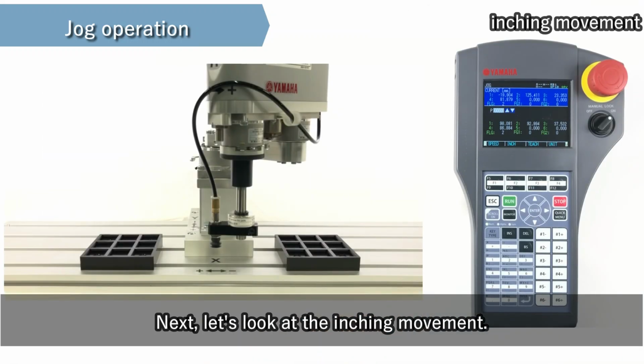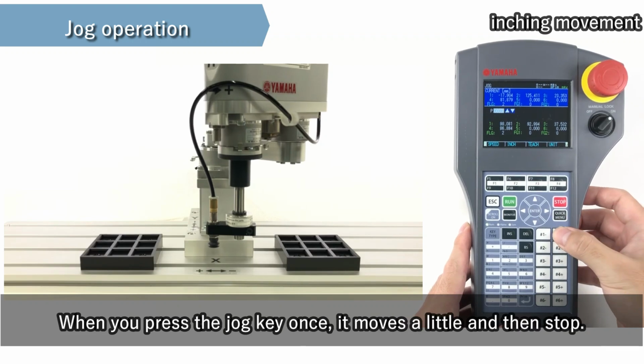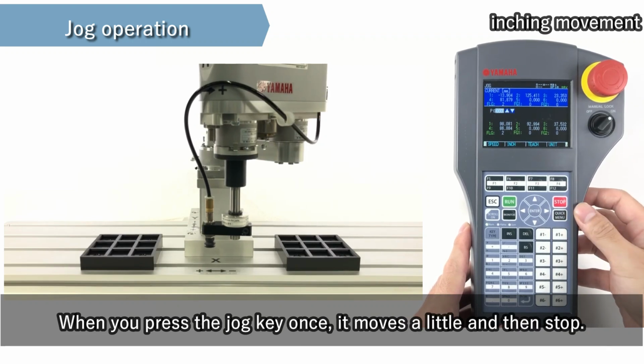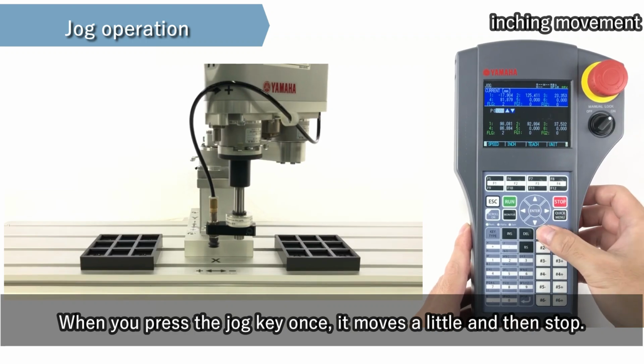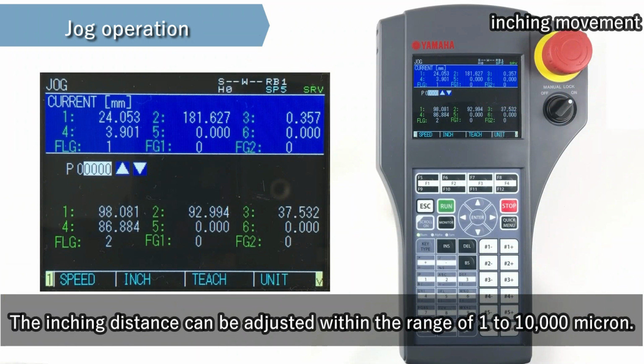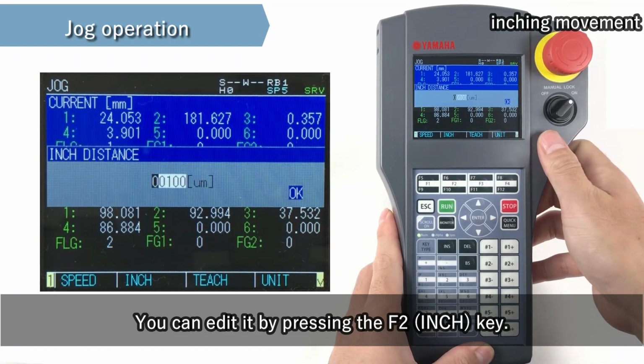Next, let's look at the inching movement. When you press the jog key once, it moves a little and then stops. The inching distance can be adjusted within the range of 1 to 10,000 micron. You can edit it by pressing the F2 key.